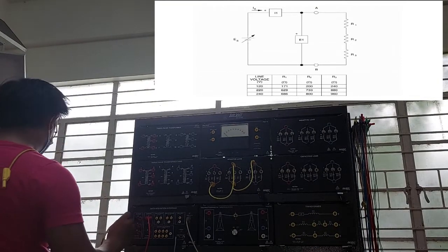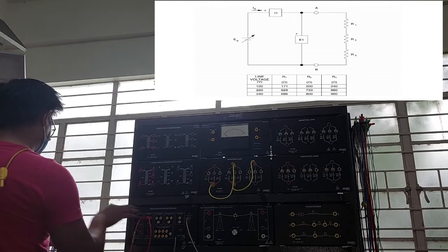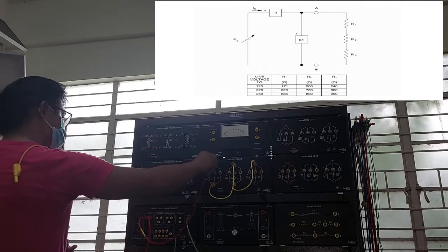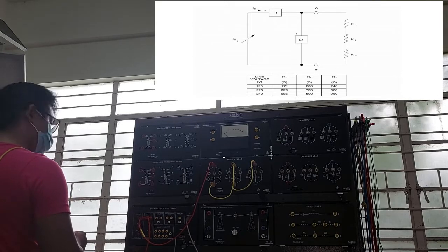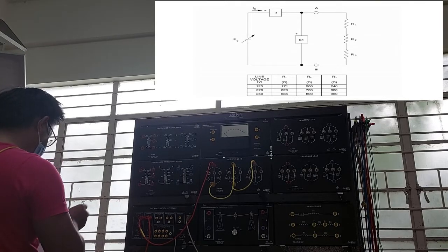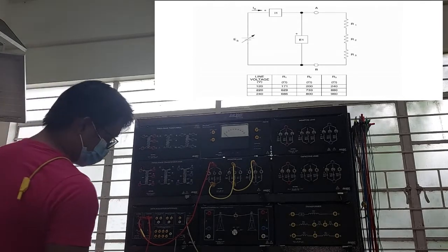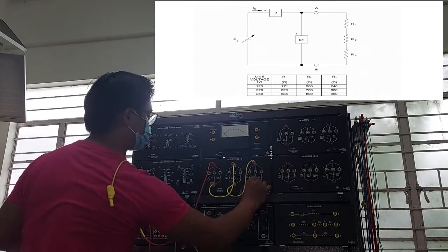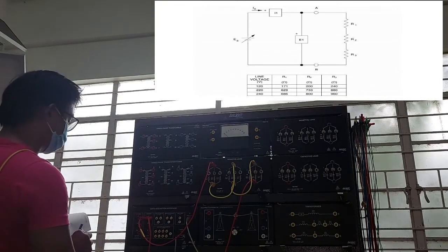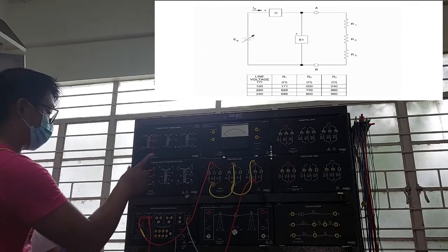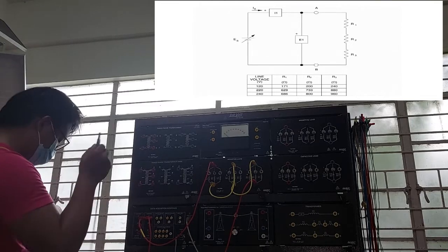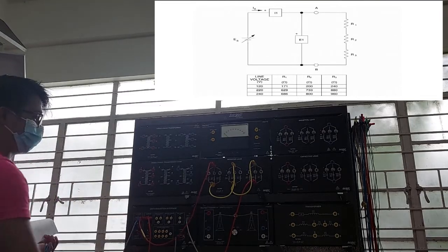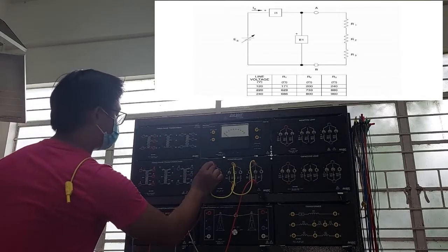of 240 ohm. So your 171 ohm value will be the parallel combination of your 300 ohm, 1200 ohm, and your 600 ohm. The 200 ohm value at R2 is the combination of 600 and 300 ohm. Take note that it is connected in parallel. Next is the parallel combination of your 1200 and 300 ohm.